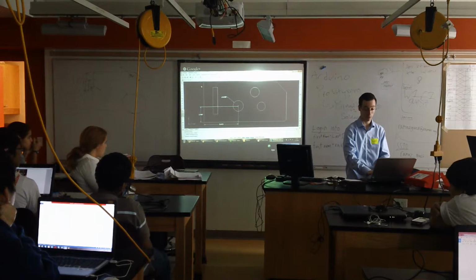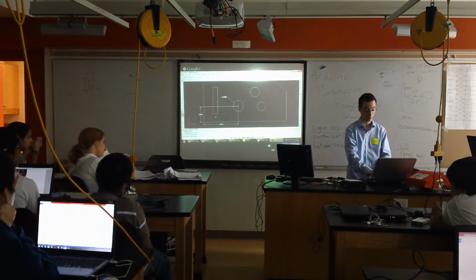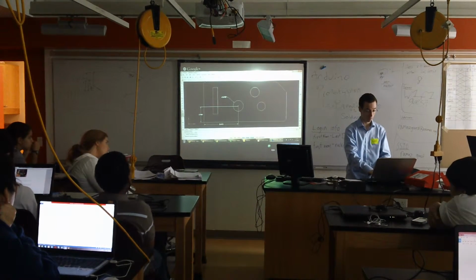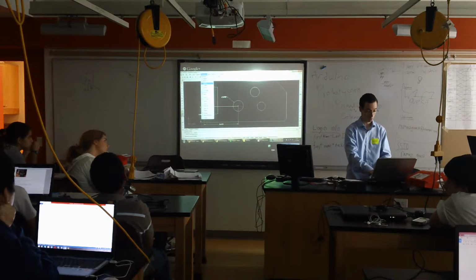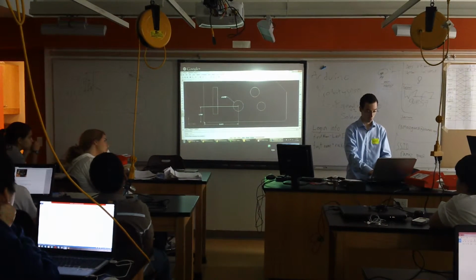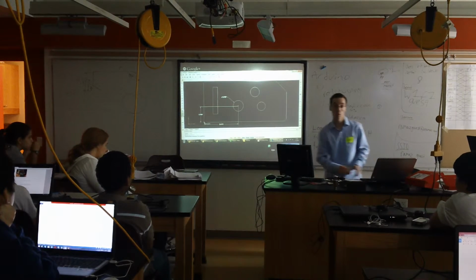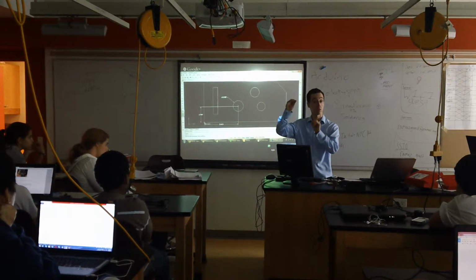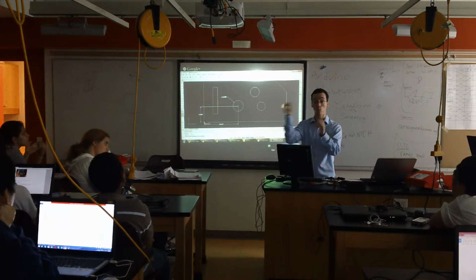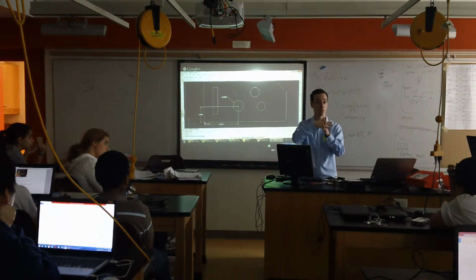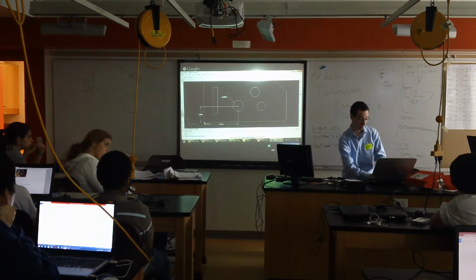Good, awesome question. So if I want to dimension this next circle here, I start Dimension Linear. It's hard to see, but when I move close to this, a little box appears around it, and it lets me snap directly to that. So the program is recognizing corners and centers of circles as important points, and will snap my mouse directly to them. So that way, endpoint.